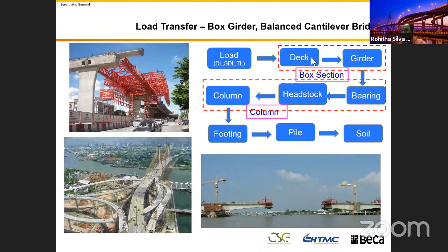These are continuous span post-tensioned bridges. You can see you have only the deck, and then you have only piles and footings. Because of that, these bridges have expansion joints and bearings, but there are very few, at 400, 300 plus meter spans. So the maintenance cost is minimum. If you really detail and design these bridges, they will last more than 100 years very easily.